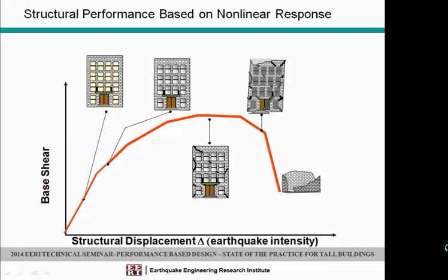And earthquake engineering snobs would turn up their noses at those firms that were doing equivalent lateral force analysis because they weren't doing this high-tech modal response spectrum analysis. Nonlinear analysis was not something that was done. So ATC 30 and ATC 40 introduced the concept of nonlinear analysis with the concept of pushover analysis. It was deemed that the really high-tech engineers of the late 1990s would be doing nonlinear static or pushover analysis.